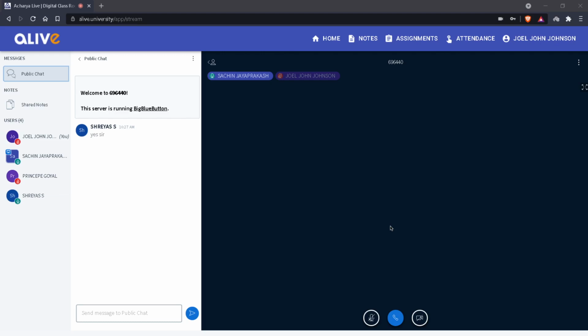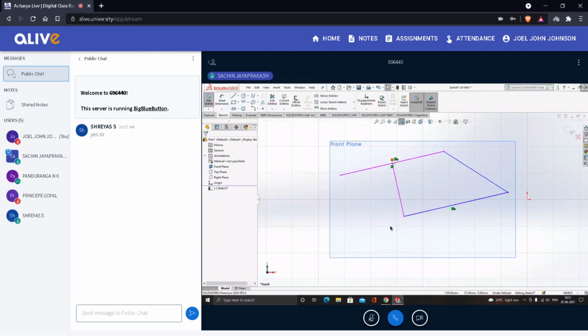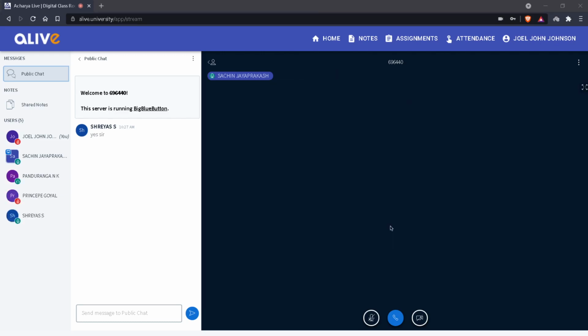Okay, so now the shape is finished. As you can see in CATIA, we were giving relations later. If it's a parallel line, or a midpoint, or general coincidence, or any other thing, we are giving it later, before getting the assembly done, or before going into kinematics.